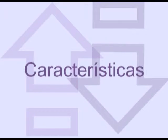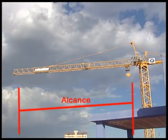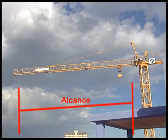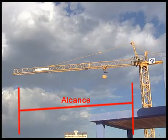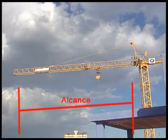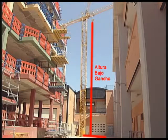Characteristics. Reach. Horizontal distance between the directional axis of the jib and the vertical axis of the hook application with no load, the crane being mounted on level ground. Height below hook. Vertical distance between base of the crane and the center of the crane's hook at its highest position.